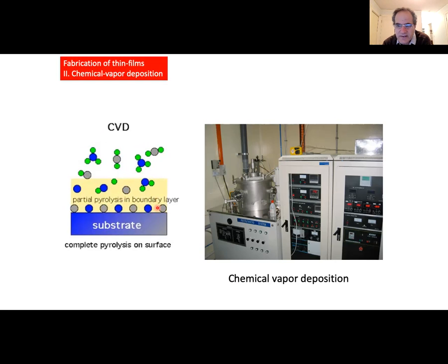So that's all, in a way, a lot more complicated than what happens in molecular beam epitaxy. But you can grow films at much higher rates. So often materials are discovered with molecular beam epitaxy, and then if there's a commercial application, someone develops a technique for growing them by CVD. And here's a CVD system here, a small one, a research class CVD system. They're still expensive, complicated machines, but they can grow at much higher rates.